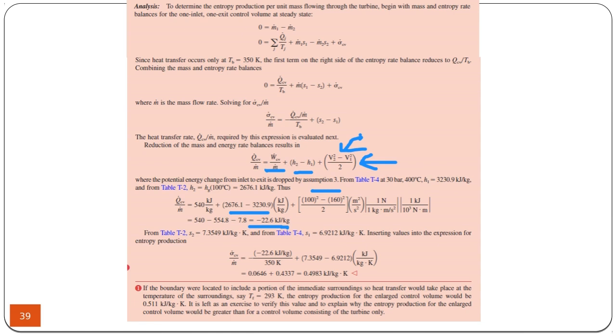So if you include this in the calculation of the entropy change or entropy generation, as you can see, because heat is lost, the entropy change due to the heat loss is negative. So this is reducing the amount of entropy production. This is interesting. However, during the process, there is a positive entropy increase, but the net change of the entropy is positive again.